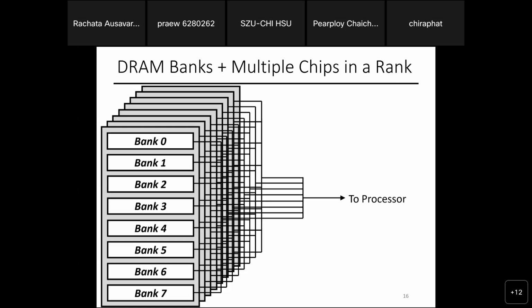You basically have to spend more time streaming the data out, so each chip doesn't send the full 64 bytes. Well, you have a choice. You can also have a really, really high pin count, which is the actual wiring that comes out of your chip, but that costs a lot. For the DRAM manufacturer, that's a big part of the cost factor because no one wants to buy $1,000 DRAM.